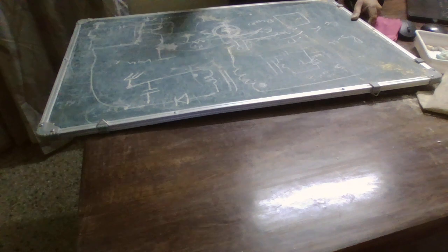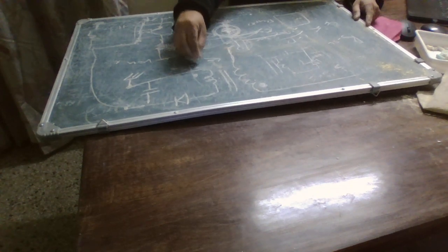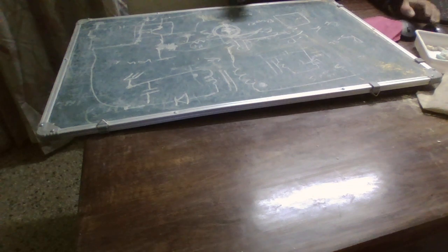Okay, that theory was explained in my last video. Besides the flyback action, the other thing that I mentioned is the reflected secondary output voltage. So the rating is going to be higher than this reflected secondary output voltage plus the maximum input voltage. Again, simple addition. And here, due to the parasitic leakage inductance of the primary winding, the switching node voltage is going to ring well above whatever value we calculate. And to avoid this ringing on the switch node, a voltage clamp can be added.